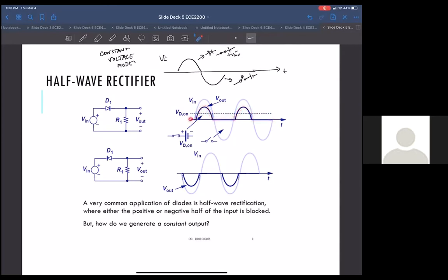So you're letting go the positive half of the curve on the output. And whereas Vin has no DC component, this actually has a DC component. If you average the signal over the full period, you only have stuff in the positive and nothing in the negative to get rid of this DC value.